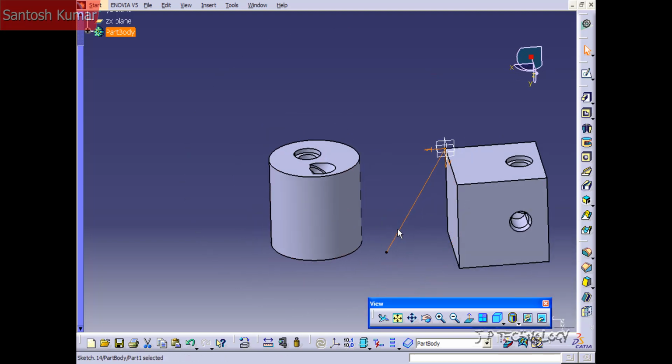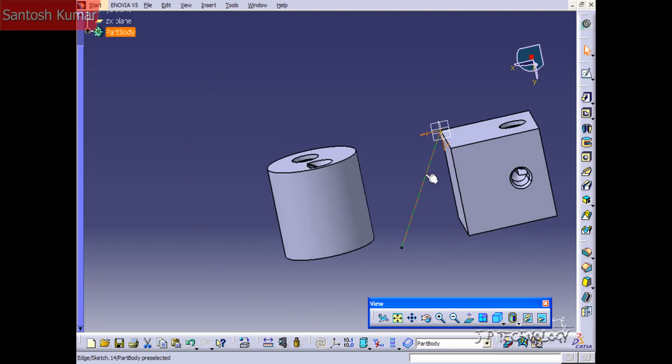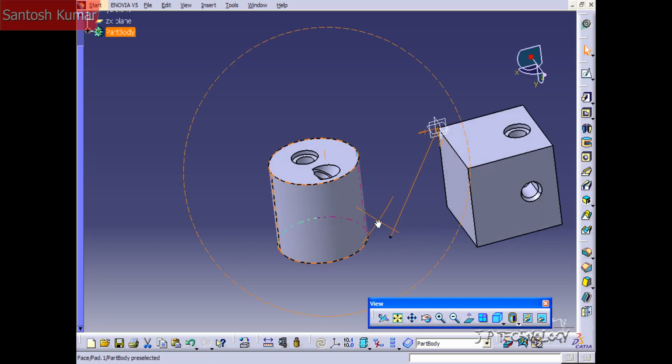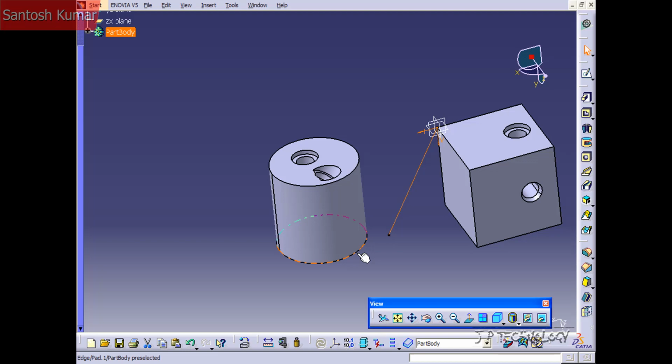So when you're making the hole, you're able to either align it with a sketch line or an edge. So say that there was actually a solid here that was along that line, you're able to actually select that line too, and it's going to follow that line. So for the hole tool, it's a very quick and easy way to make holes, and especially if you're making the counterbore and countersunk, you don't have to worry about making all those different kind of sketches. It gives you all the tools and all the parameters to quickly and easily make holes within CATIA. And that concludes our tutorial on the hole feature within CATIA V5.